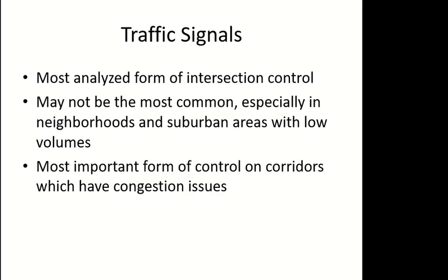Okay, but in areas which have low traffic volumes, we do not usually prefer providing signals, which you may have seen on most of the local streets in Bahrain as well. But when the traffic is very high, the corridors or the routes which have high traffic, the signal also becomes the most important traffic control device there. Okay, because you need to have some intersections there, even in those corridors. You cannot make everything signal free.